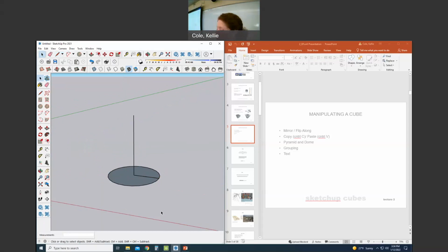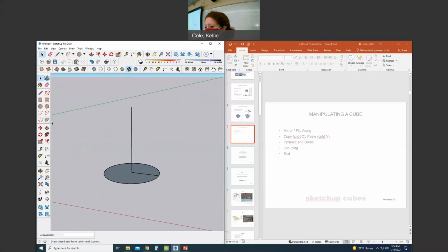And I'm going to use a new tool. I'm going to use the 2-point arc. Again, this one doesn't have a shortcut. I'm going to click kind of in the group where the L line is. And can you guys see my screen, right? On your screens? Yes. Good. All right. So 2-point arc, we're going to click that. Then I'm going to pick 2 points: the top of my vertical line, the side,